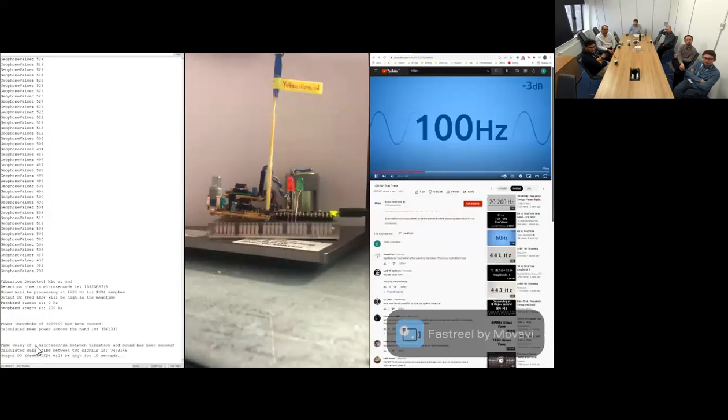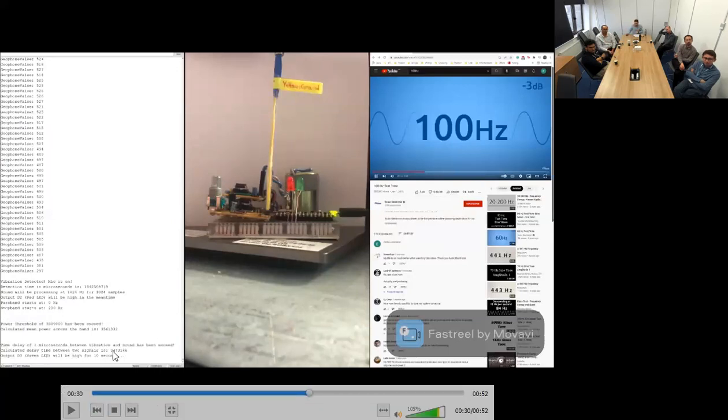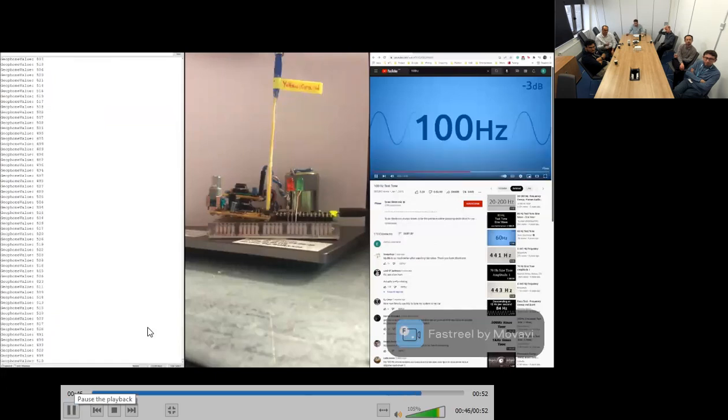I put just 1 microsecond to check if the code is working or not. Then I put 10 seconds of digital high if all the conditions are met. So after 10 seconds, it gets back to the initial state, which is checking the geophone value, and it does. So the prototype device is working as expected.